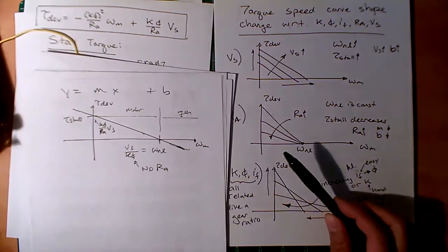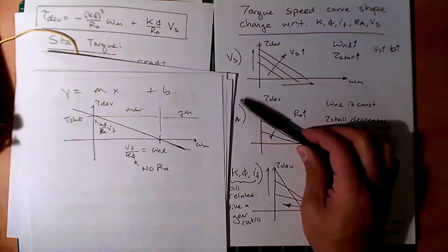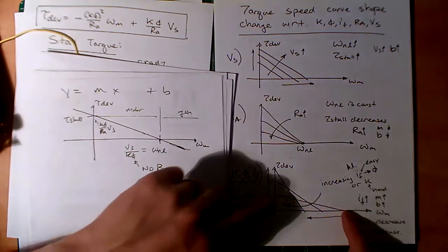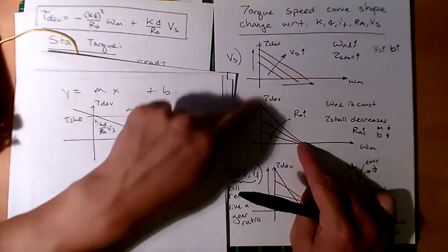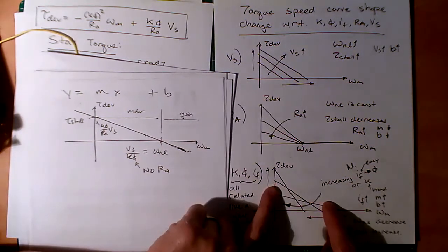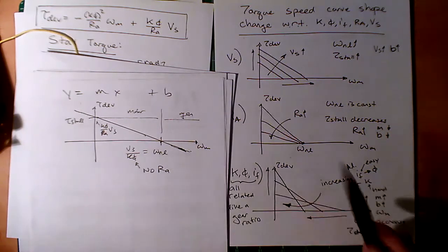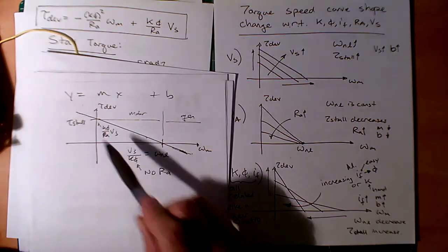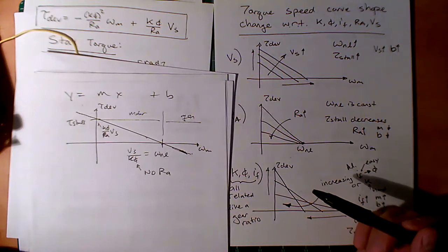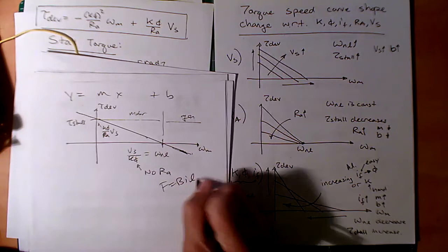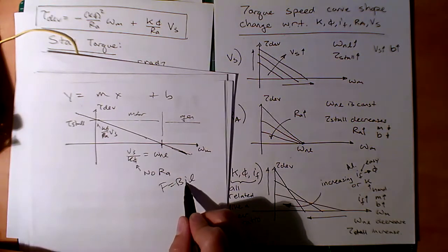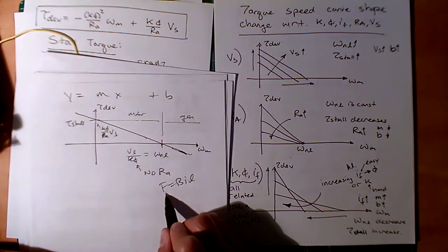And let's think about why you get a rotation, and not only just a rotation, this translation of these two points, whereas here you get just a rotation about that pivot point. If you have more flux or flux density, which is represented by the phi, your Lorentz force equation, F equals BIL, is going to take current here and give you more force, right?